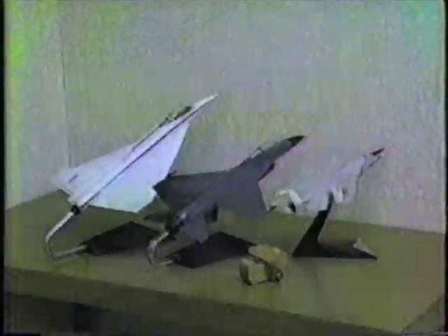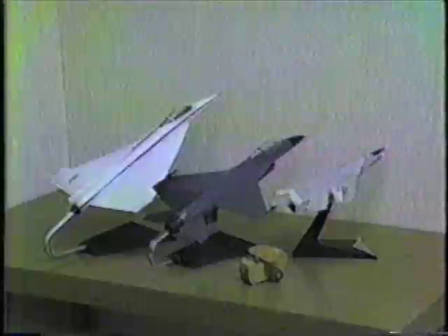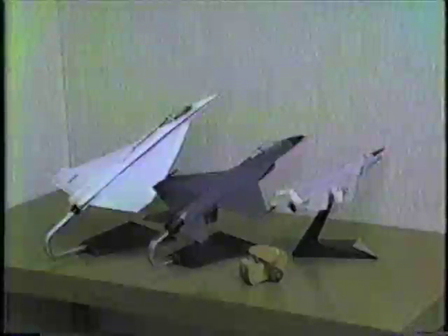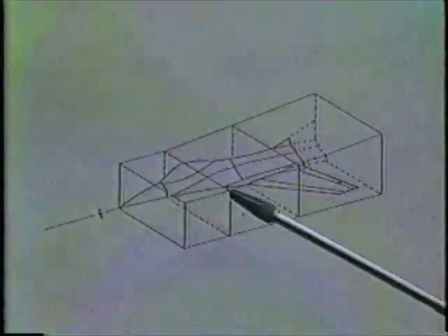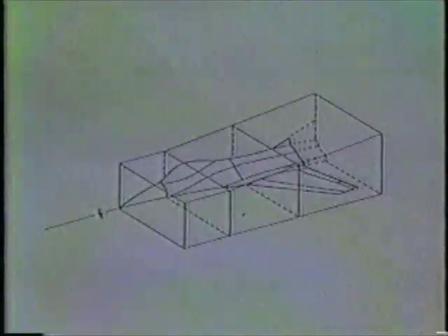Such a numerical solution requires that the flow field domain be represented by a number of points, commonly referred to as a grid. The surface shape, the differing length scales, and complex aircraft geometries make it impractical to model the flow domain sufficiently with a single grid. Therefore, we divide the flow field into a number of zones, referred to as blocks. This idea allows very complex geometries to be modeled.